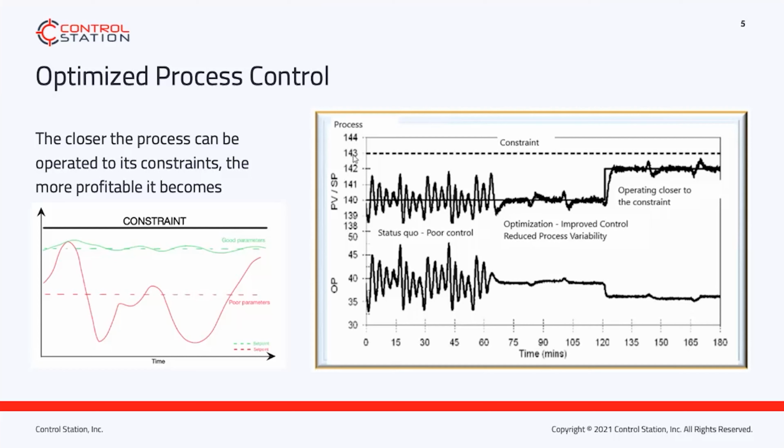PID controllers are the most widely used controller in the industry, and it is a known fact that many of these controllers are poorly tuned, and some have never been tuned at all. It's not uncommon to observe loops with self-induced oscillations because of excessive integral action, or finding a cascade loop where the outer loop is tuned much faster than the inner loop.